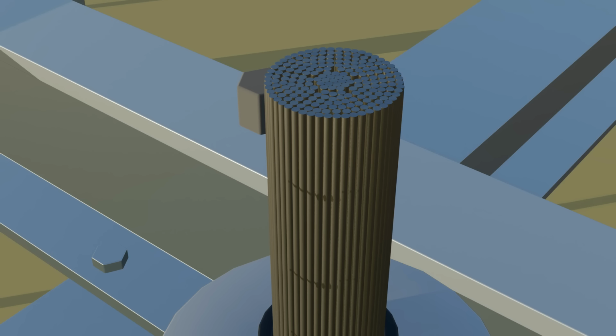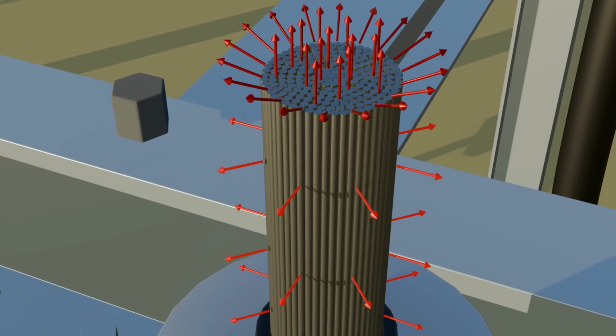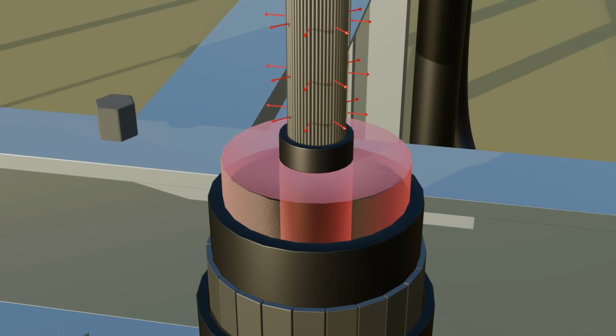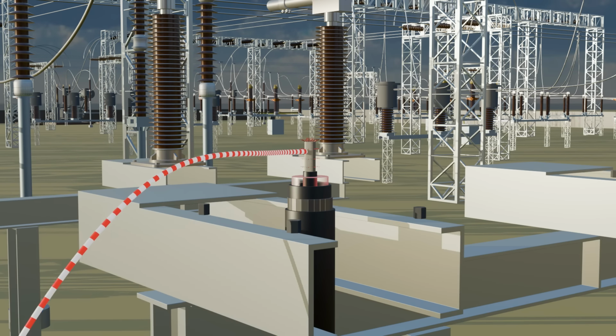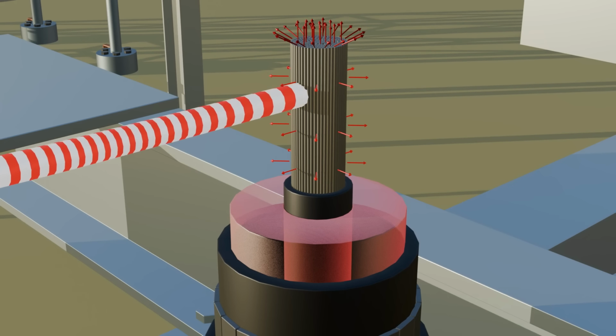When the cable conductor is cut, the electric field starts concentrating strongly around its sharp edges. If this field is not controlled, the cable insulation can be damaged. This may allow the conductor to come into contact with Earth, causing a major fault. To understand this, we need to look at the cable design.